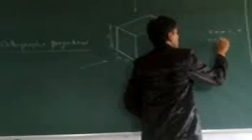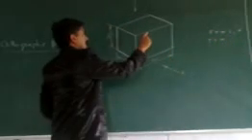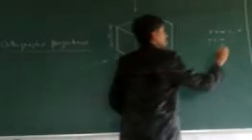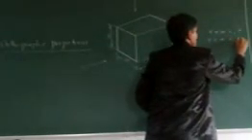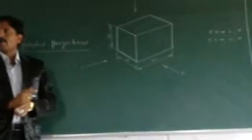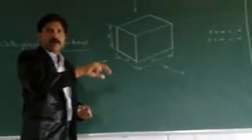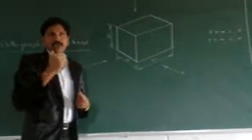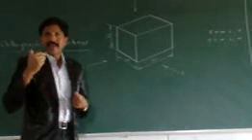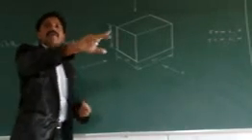In the top view, we should observe only the length and width. So the dimensions are length and width in the top direction. And next here, the visible side is only the left side. Why? Because at the right side, the shape is covered by the whole object. So whatever the actual shape which is visible in the direction of the side, we should select only that direction to observe the given side.